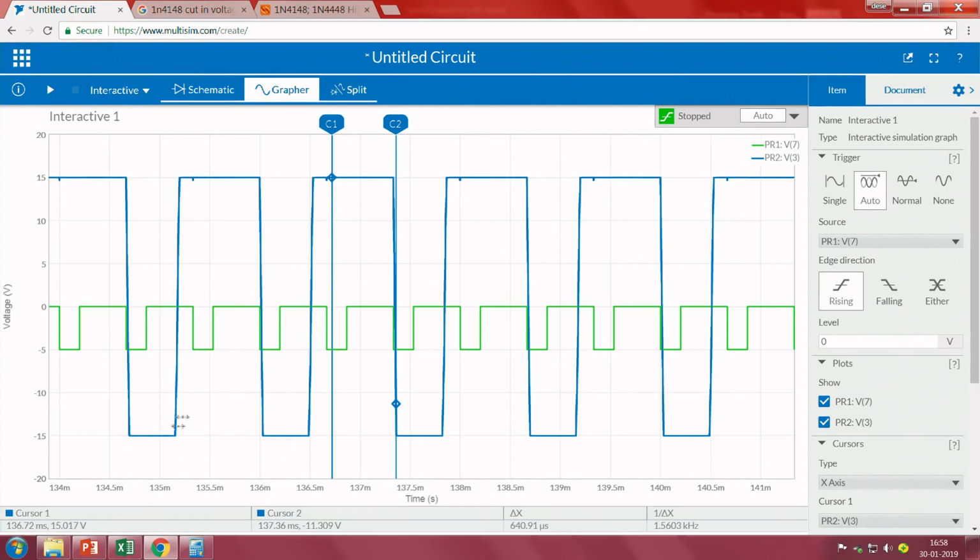But if you observe, since I don't have enough room for the capacitor to discharge, it is not able to detect the negative signal from the encoder pulse, and it is becoming low again only when the next sequence arrives. As a result, over 5 or 6 signals we are losing 2 or 3 peaks. So the accuracy of the system is decreasing. This is because of a design constraint, not properly choosing the charging and discharging rate of the capacitor. That entirely depends upon the R1 and C1, the resistance and capacitance that we have chosen in the design.